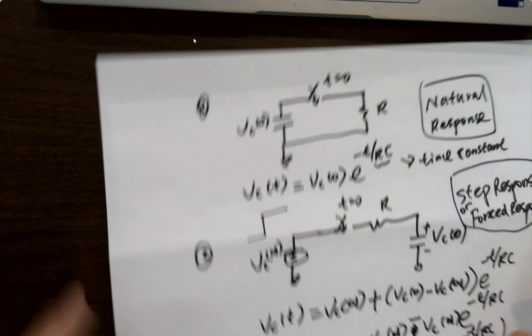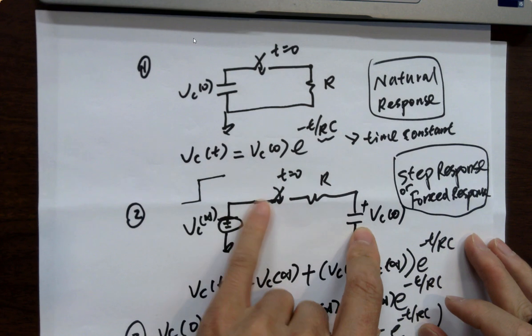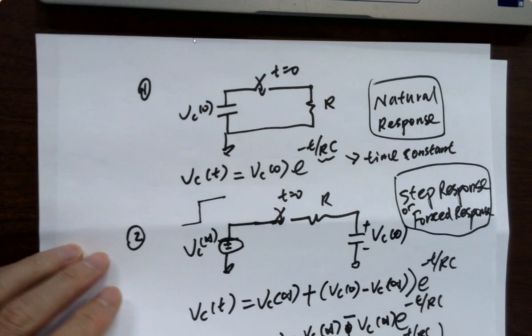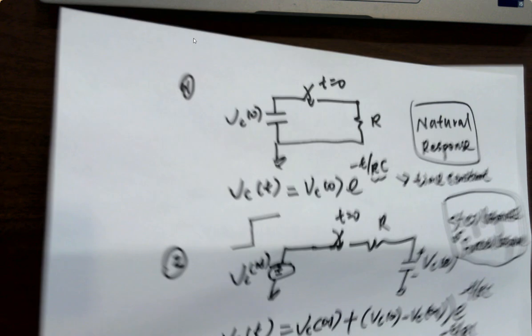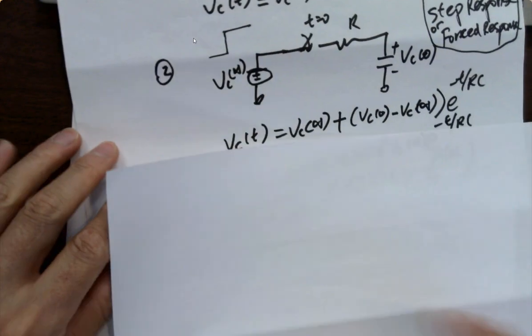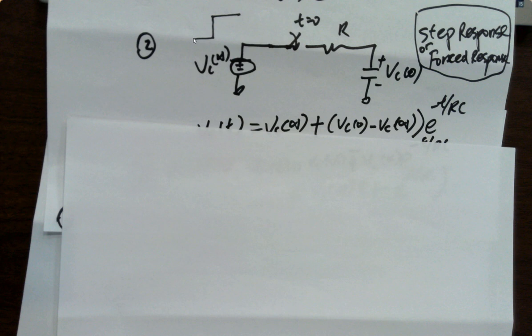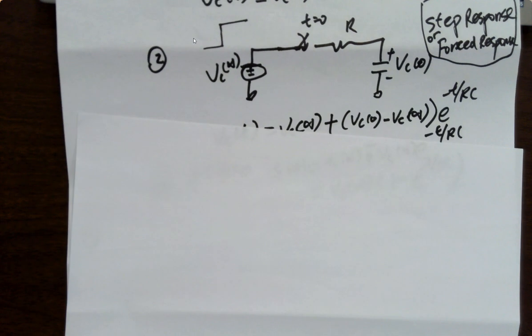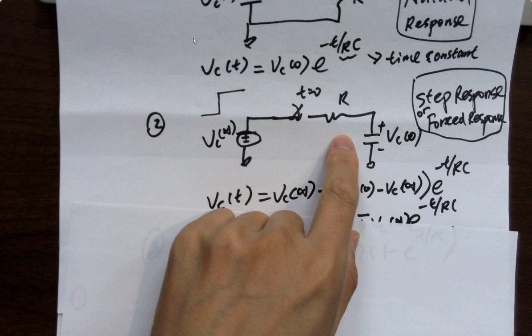Because all these digital circuits are actually driving an RC circuit over time, like the CPUs. The reason for that is the cables are not ideal conductors, so they have internal resistance, and all the cables have a rubber shield and all the silicon dioxide in the chip, so they are forming dielectric materials and forming capacitors, right? So basically, all these capacitors and resistors are everywhere. Because eventually, when you are driving a CPU with a high frequency, it is actually driving an RC circuit like this. So you will have time delays.